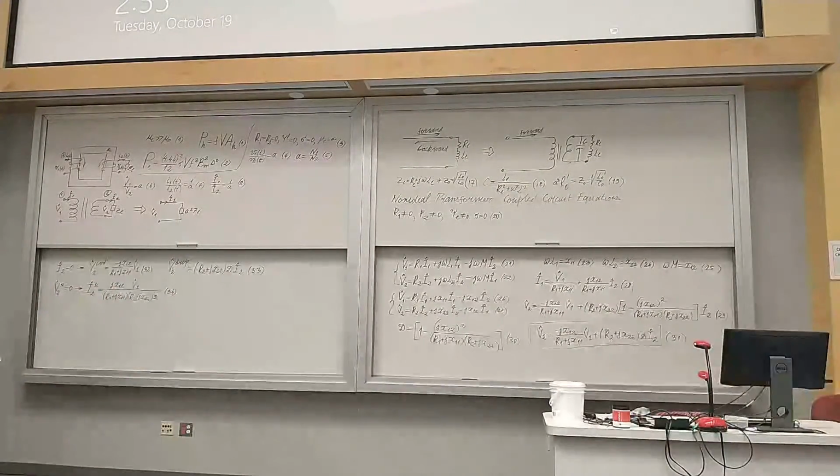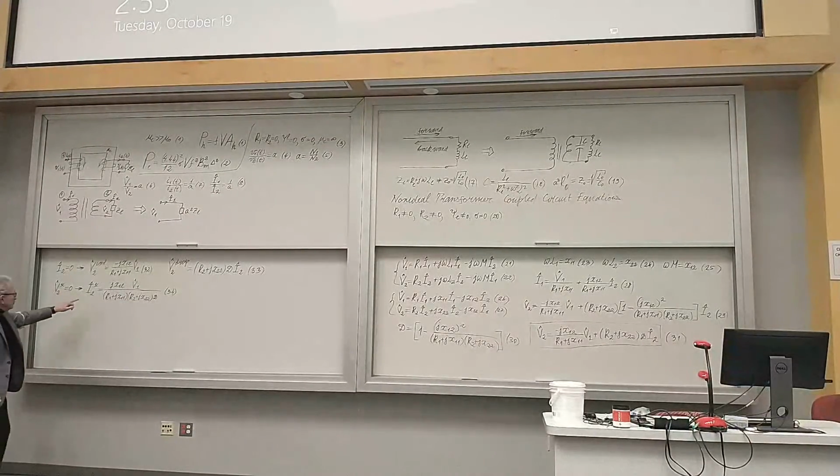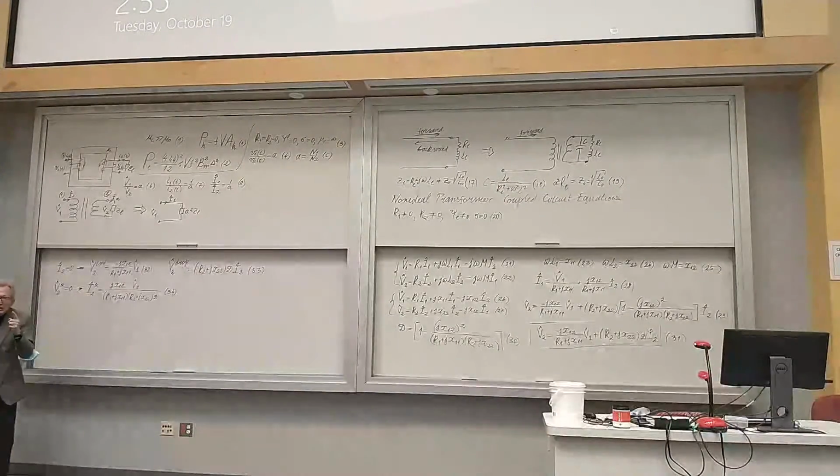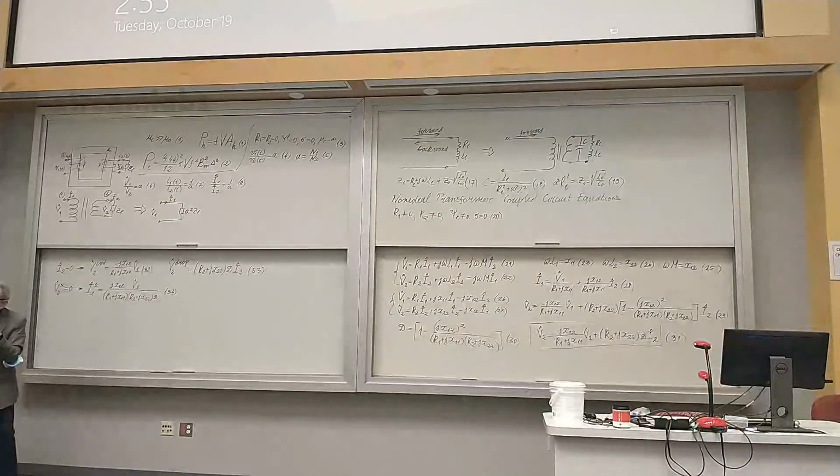And we can see the smaller the d, the better the quality of the transformer, the more it's sensitive to the short circuit situation. It results in larger short circuit current. So there is nothing fantastic. If you would like to have a very good quality transformer, that is, maintain more or less constant voltage in the face of continuous or predictably changing load, you can achieve this by using small d, but then you should pay for a very good protection system, relay protection system, to switch it off very fast during the short circuit situation.